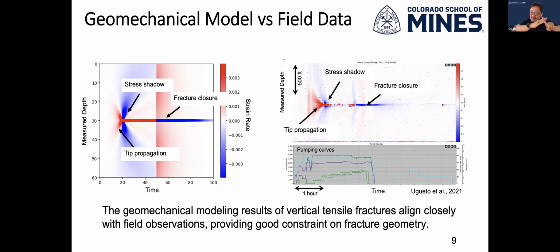This turned out to be a really powerful tool, even with these very, very simple diagnostics. It turned out to be a really important tool to understand the fracture geometry, simply because of the really, really high spatial resolution, we're able to identify individual hydraulic fractures. Remember when I talked about the microseismic, at the stage level, we can roughly see the fractures growing in that direction. But now we are able to see individual hydraulic fractures that are propagating in the subsurface.